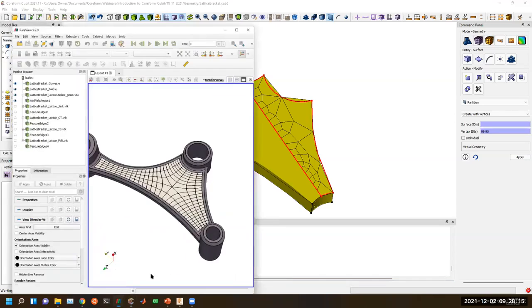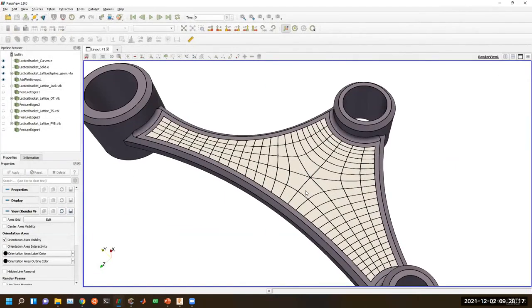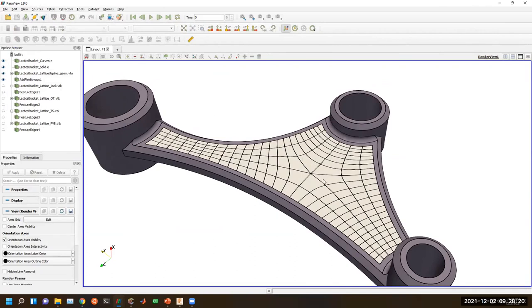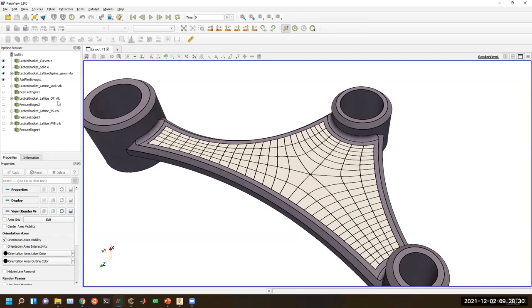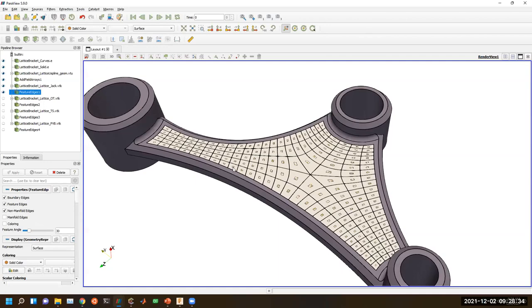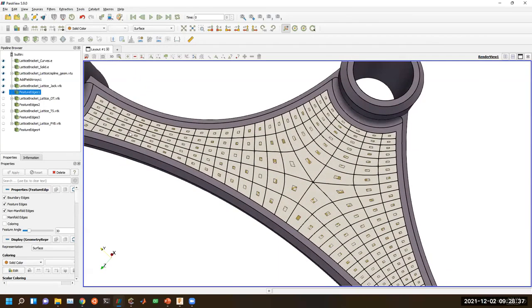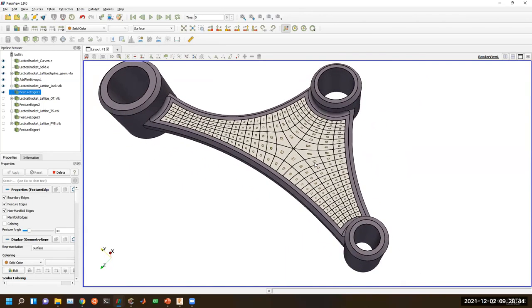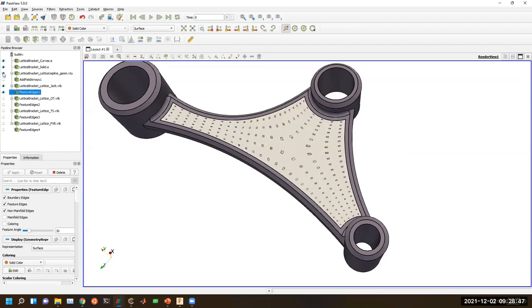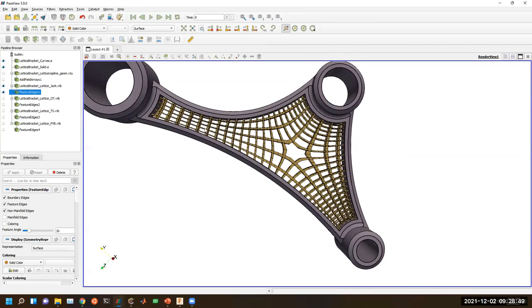So just as some results we can get out of this, I've pre-baked this solution here with the polyhedron mesh. Again, I had done some splitting and then compositing after the fact to get out this mesh. And if I put in some lattices, we can see the layout of these lattice structures within these cells. If I now turn off the U-spline mesh, we can see this lattice layout.